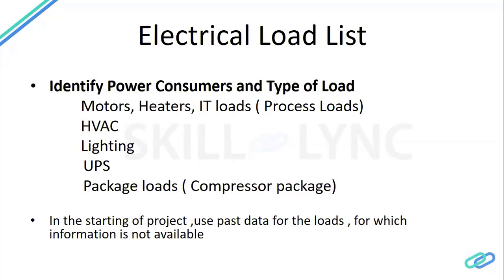But a compressor is not only a single motor. Small motors come with the compressor for cooling, for heating, and for some other purposes, which you don't know in the initial stage. So you need to coordinate with the manufacturer and get all the input. That's why this is an important part. You can't afford to miss these things. Otherwise, at the last stage, you will have a problem in the transformer sizing.